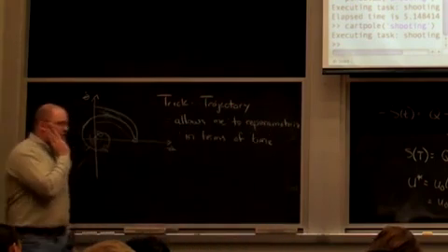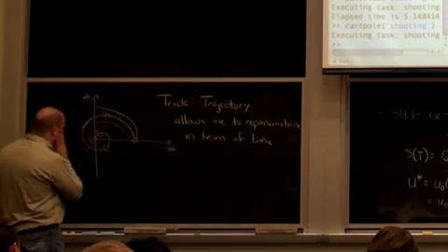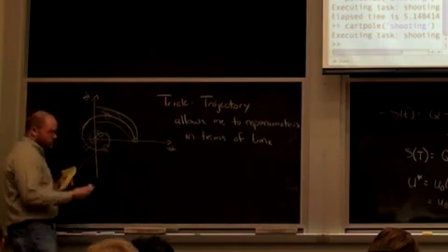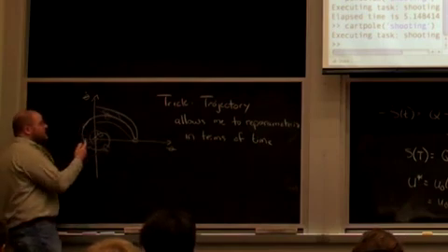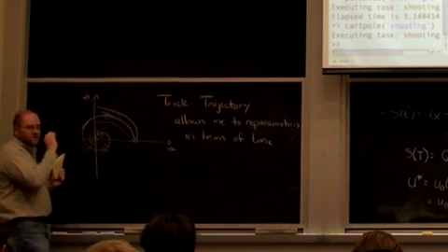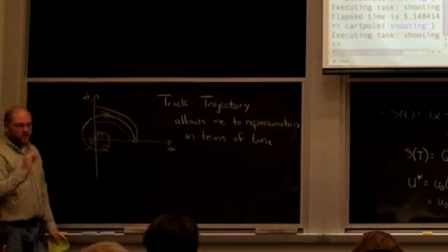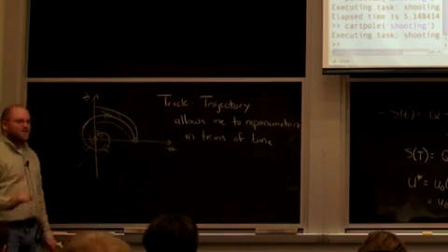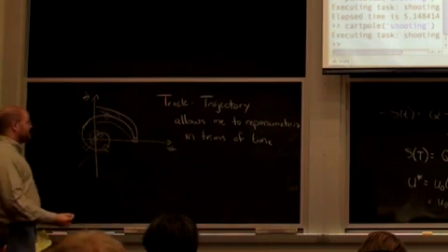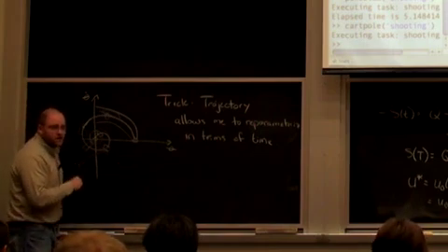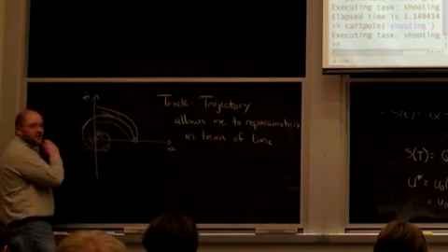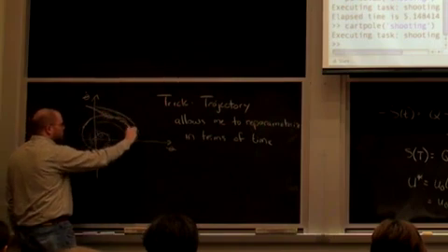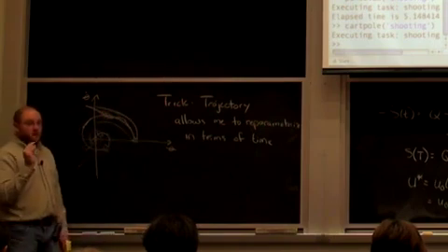When I first started working with it, I thought that it would have the property that it uses a lot of control to force itself back to the trajectory and sort of rigidly follow the trajectory, right? It's easy to equate linear control with sort of high gain linear feedback, which people do a lot of. Okay, but it doesn't necessarily need that property. If R is small in this derivation, it can actually take very subtle approaches back to the trajectory. Your system might come in and do whatever it needs to get back on the trajectory with very little torque.